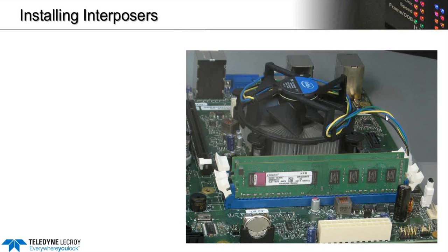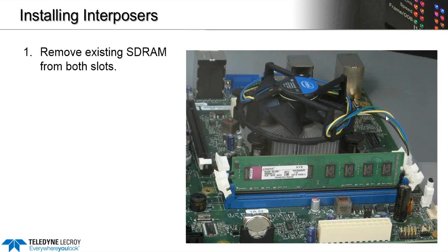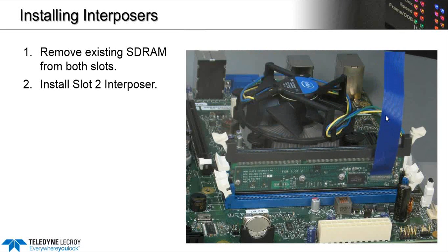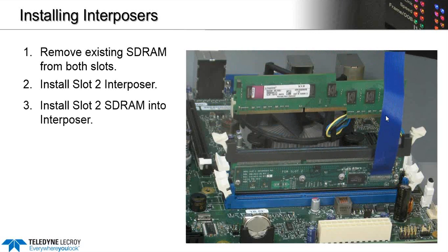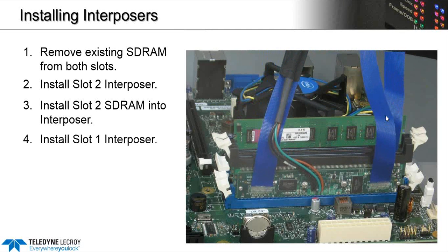The analyzer uses a slot interposer style probe which sits in line in the DIMM slot. You remove the memory, insert the probe, and then put the DIMMs on top. These are actually UDIMMs in this picture, but some good news: DDR4 RDIMM and LRDIMM are going to continue to use the same connector as UDIMM. So we have a single interposer that can be used to basically test both unbuffered and buffered DIMMs.